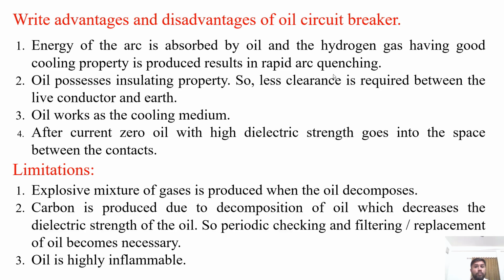The limitations of oil circuit breakers are: an explosive mixture of gases is produced when the oil decomposes, and carbon is produced due to the decomposition of oil, which decreases the dielectric strength of the oil. So periodic checking and filtering or replacement of the oil becomes necessary. Oil is also highly inflammable. So these are some limitations of oil circuit breaker.